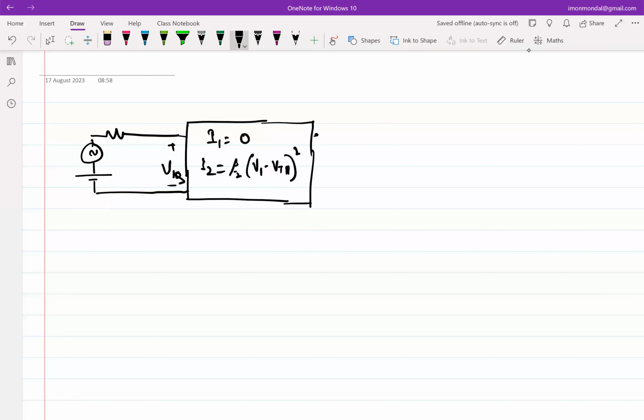Similarly, it was not sufficient to simply connect the load resistance RL directly across the output port, because we had to honor the output side condition of the transistor being in saturation, right? So V2 should have been at least higher than V1 minus the threshold voltage. If we had to honor that, we understood that we have to put the load resistance in series.